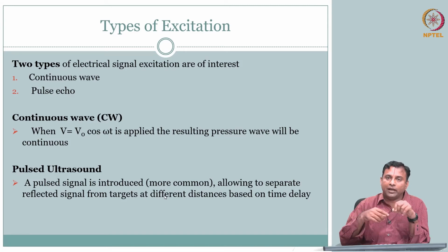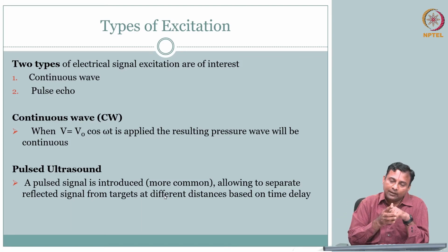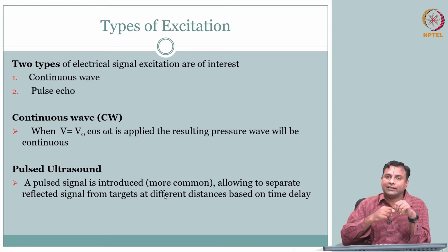It gets bounced back, as we saw, right? Reflection, refraction, and then your scattering, all that happens. So some amount comes back. When it comes back, it is hitting your crystal, right? Matching layer and then your crystal. So when that happens, that is converted to your electrical signal.